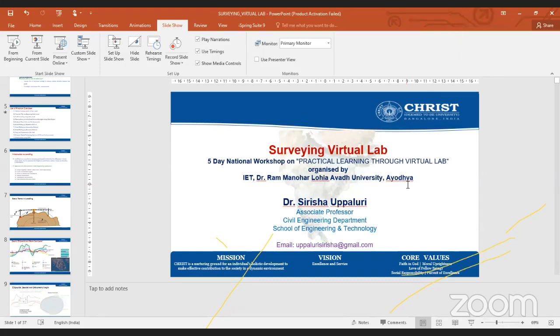In the normal position, the line of sight will be horizontal. But the telescope terminology is actually applicable to the theodolite. In leveling, generally the line of sight will be horizontal only. We say staff inverted, not telescope. The terminology is applicable to theodolite surveying. Here we are going to take a staff inverted.